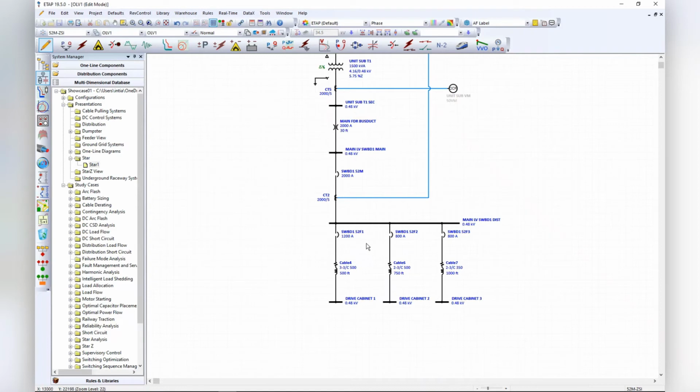So you couldn't have a fault that falls in the instantaneous between this feeder and this breaker and have a selective interlocking scheme going on. It doesn't exist, as far as I know, for Eaton at least. It needs to be on the short delay region of the coordination.